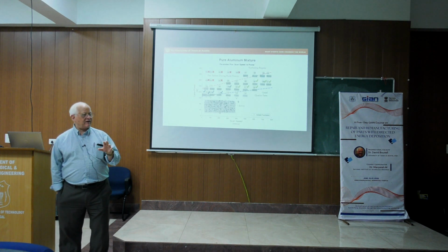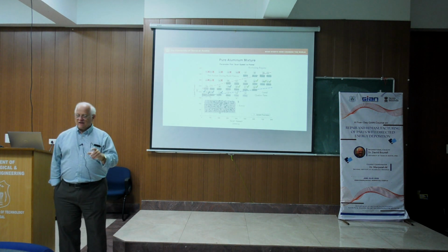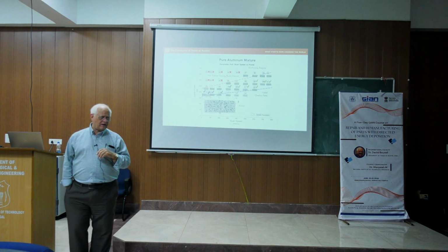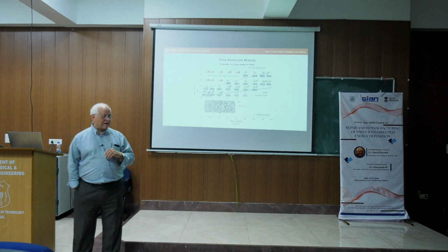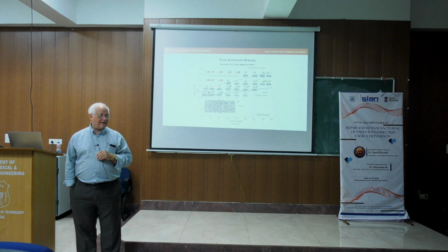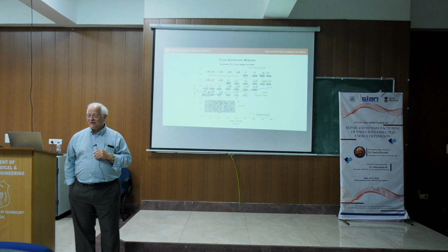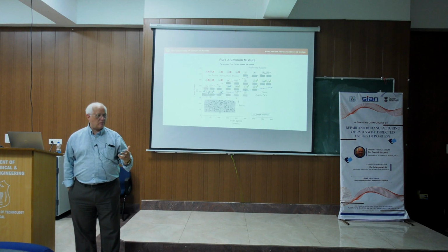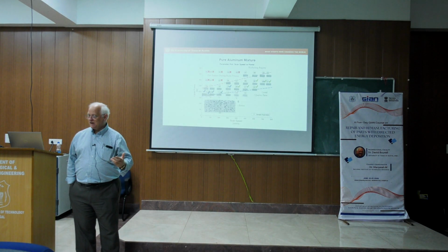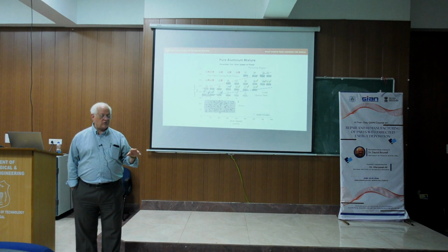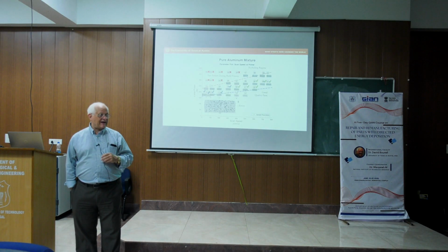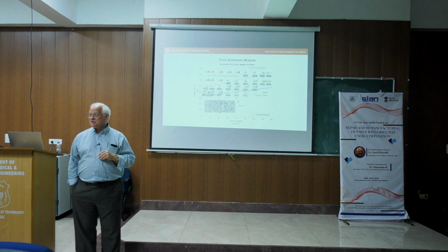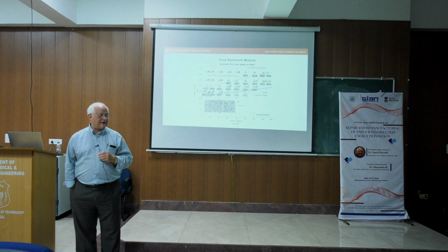Because if we have a given metal, if I do a tension test, I'm not going to get a yield strength of 200 megapascal every single time. There's going to be a scatter. And it turns out that if you look at large numbers of tension tests on lots of raw material that is supposedly identical, there could be as much as a 10% variation in the mechanicals.